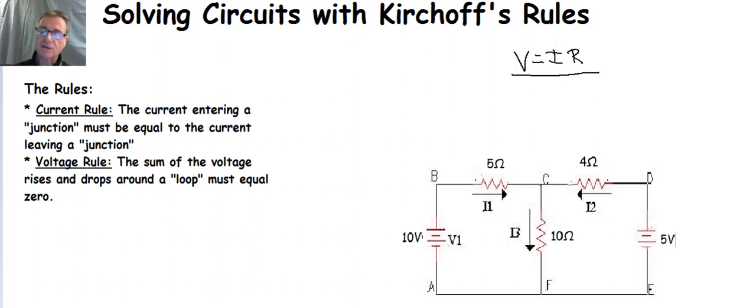If you look at the screen here in the lower right-hand side, we see a circuit with two loops. It's a combination circuit because it's not just a parallel circuit, and it's not just a series circuit. One other thing that is interesting about this circuit is that we don't have just one voltage source. We have a 10-volt voltage source over here and a 5-volt voltage source over there. And the question is, what do we do with these? How can we determine what the total current is, or the current in any one of the loops of the circuit? Well, this is where Kirchhoff's rules come into play.